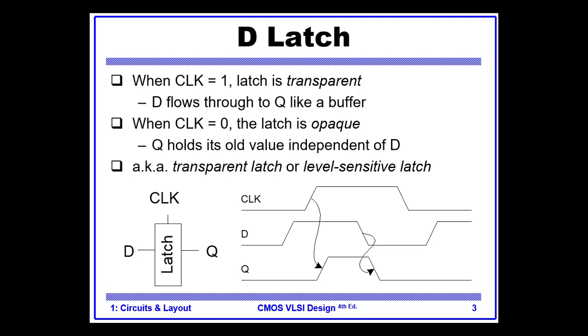So as I told you that it depends on the gate or clock. So this is the gate or clock. Okay, so when clock is 1, the latch is transparent and D goes to the output, as I told you.